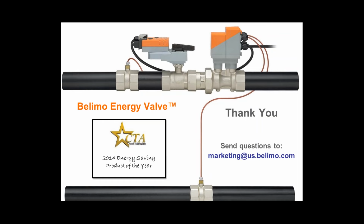Okay, and we have one more question. Are there any piping requirements due to the flow meter? Yes, actually, that's a good question. There are. We request that there are 5 straight pipe diameters leading into the flow meter. So if you're looking at the screen right now, water would flow right to left into the energy valve.